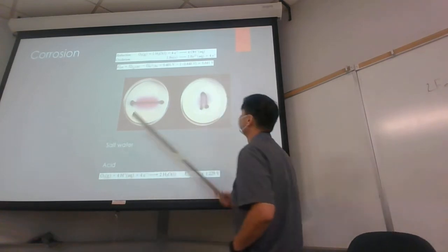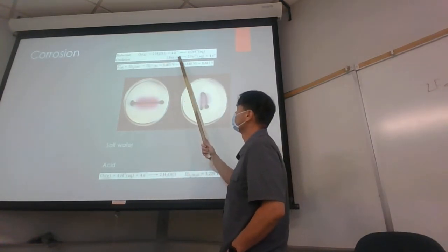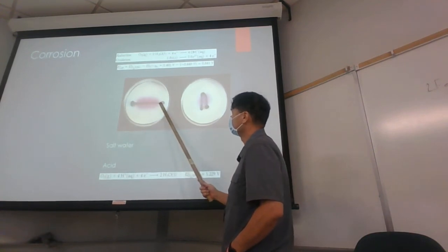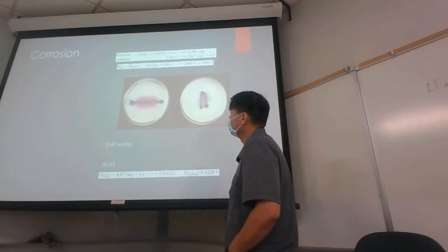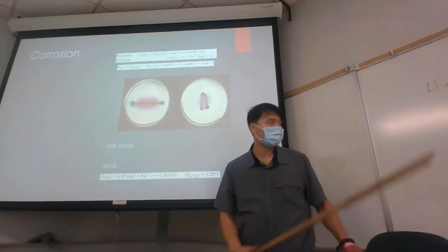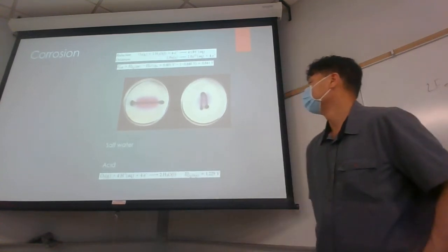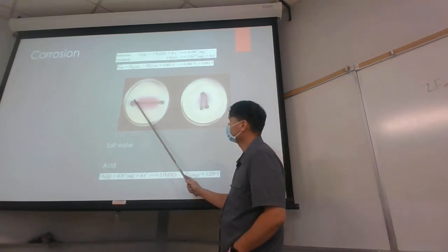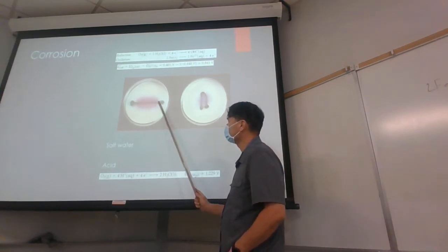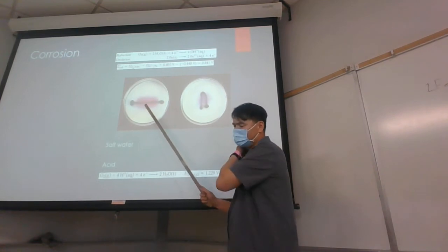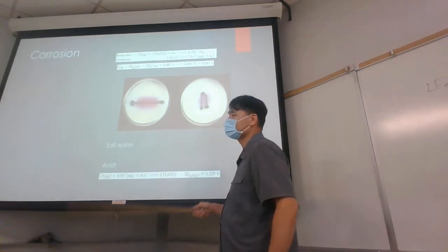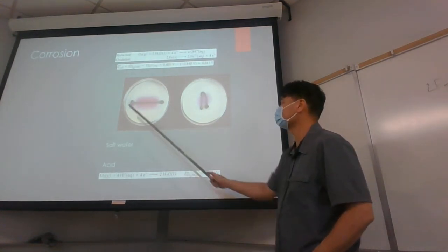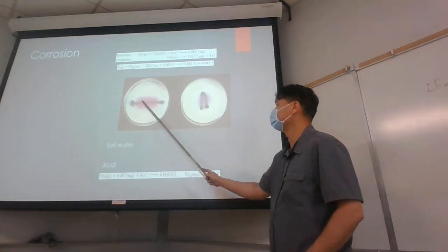And so what we have here is iron. I go through this in lecture as well. Iron's the anode, so we have an iron nail here. And to further study the process of corrosion, you take this iron nail and hammer the ends. When you hammer the ends of the iron nail, it introduces defects. When you put in defects, that makes those atoms even more susceptible to oxidation. So it's easier to oxidize the atoms in the ends than these atoms here.